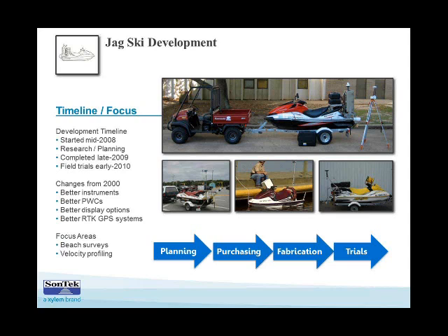Let's go over a few tips and tricks. Bullets will come up one by one as you click. So I can't really emphasize enough the importance of doing some reconnaissance at your site, before you go out for an initial survey and before you go back for a follow-up survey or routine surveys. It's really important to go out and get a grasp of what the site's like and what the conditions are like. That's going to help you a lot with your line planning.